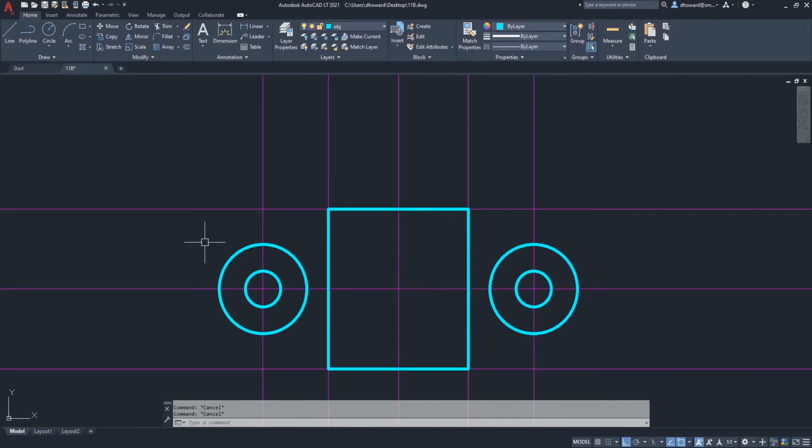And then you would just connect them. So in my line command, I can come over here and grab hold of tangent snap. There it is. Same over here. I'm hitting the enter button to get out and the enter button to get back in, and there it is. And I'd like to point out how the nearest snap right here is giving us trouble. Look at this. The nearest is popping up right next to tangent, because the thing with nearest is that it basically grabs hold of wherever the cursor is near to a line or an arc. So you got to make really sure you have that right.